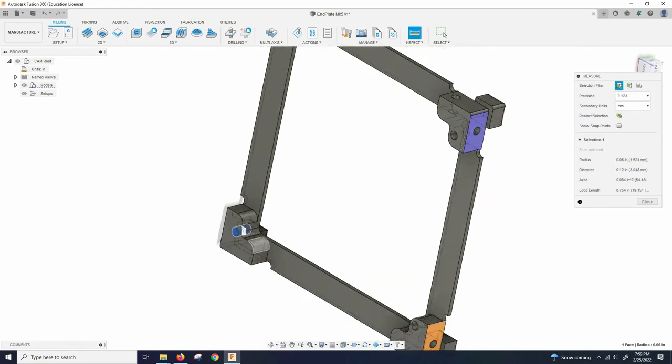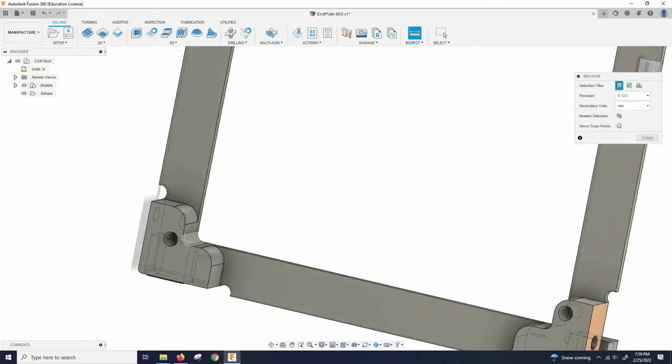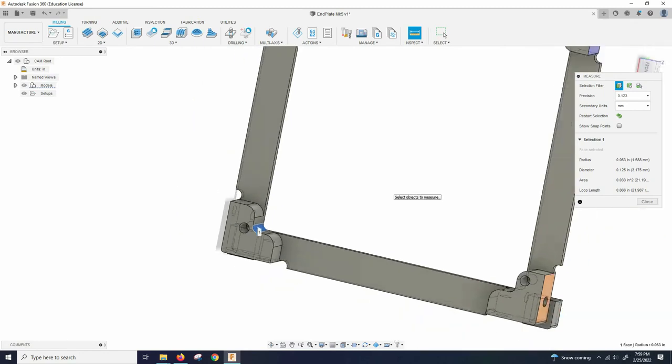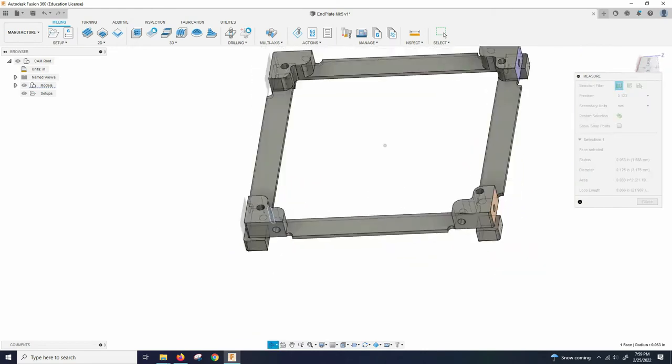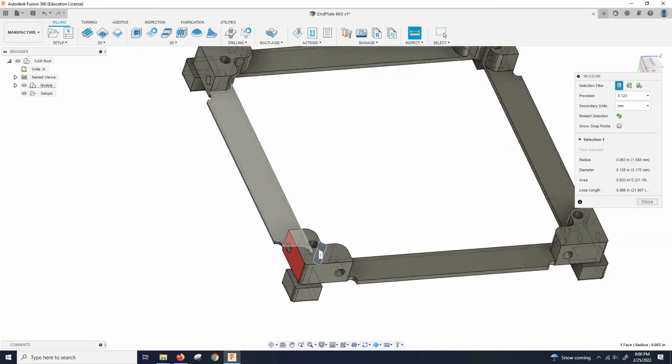And then if you look at internal features like this radius here, not the measurement between those, the radius here, usually the diameter is 1/8 of an inch or 3.175 millimeters. So thank you, NASA, for being a US company and being mixed between inch and metric units. Because all of the tooling that we have is in inch units, we are going to do all of the machining in inches. So I might refer to millimeters, but everything we do is going to be basically a fraction of an inch. So 1/16, 1/8, half, things like that.